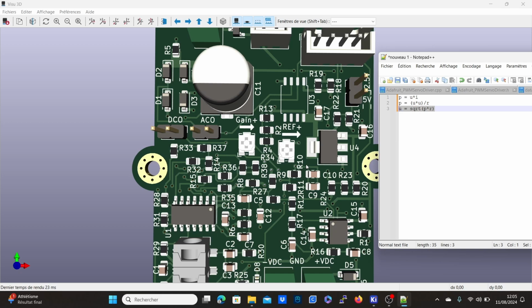And usually the 0805 is really a classic, it's going to work well for a lot of electronic devices. So yeah, it's usually safe to just use those ones. But if you have space constraints and you need something that's smaller than that, you may consider using this formula to just make sure that the components will be able to withstand the voltage you're planning to use.